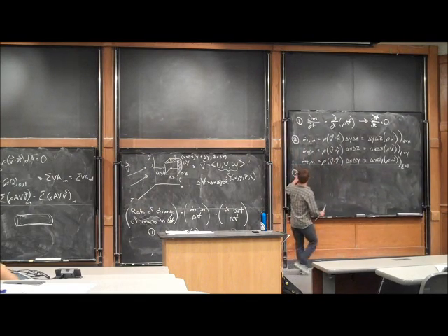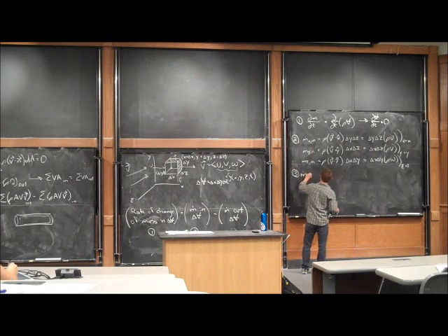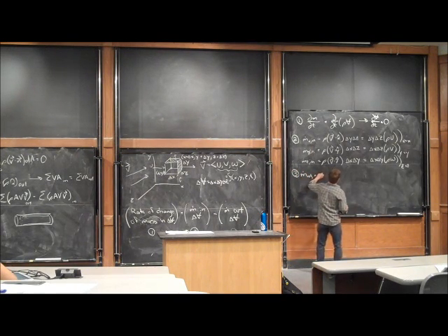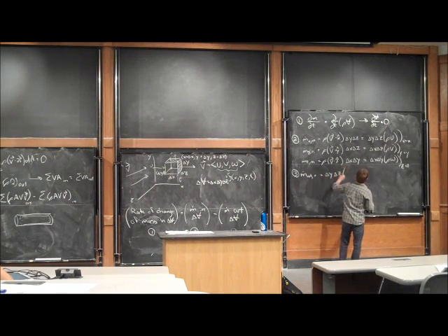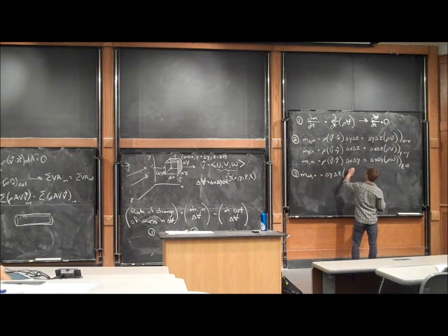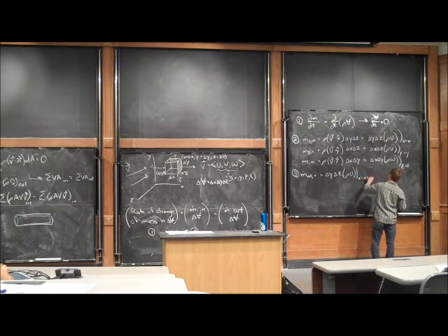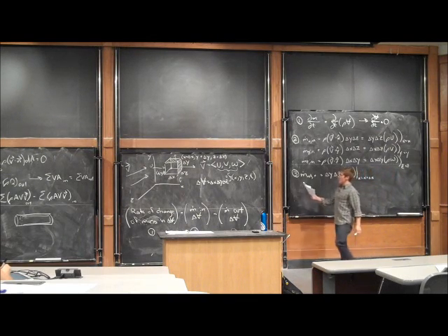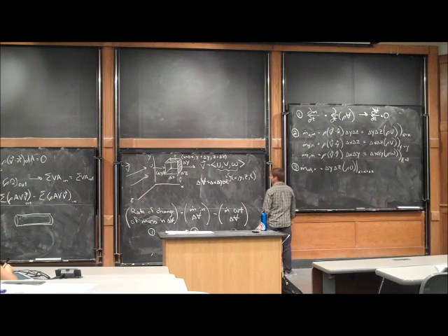So our outflow in the x direction is going to be defined delta y, delta z times rho u, but now this is rho u at x is equal to x plus delta x. So we have moved one step forward, and we're having a different flux of mass through that opposite side.